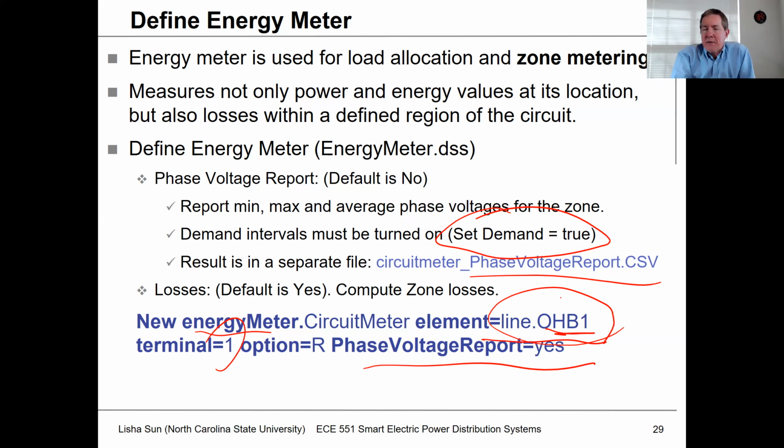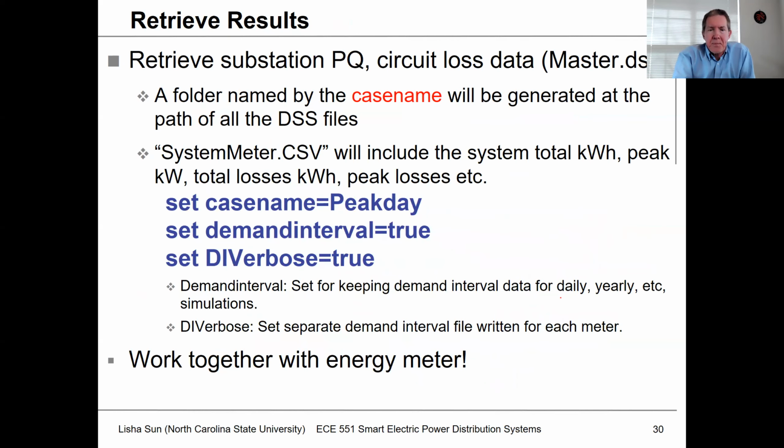Once you start using OpenDSS and you read the documentation, this will be a little clearer. But again, you have to put a lot more effort into finding your output results. It doesn't automatically print out a bunch of reports like Windmill does. You actually have to go and tell OpenDSS specifically what it needs to give you as far as results.